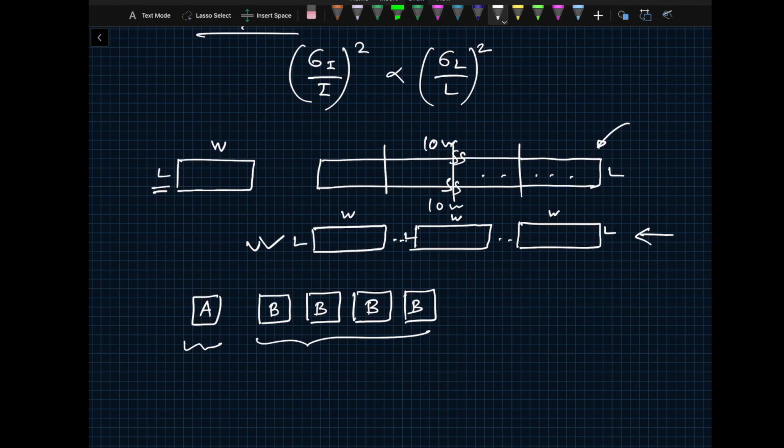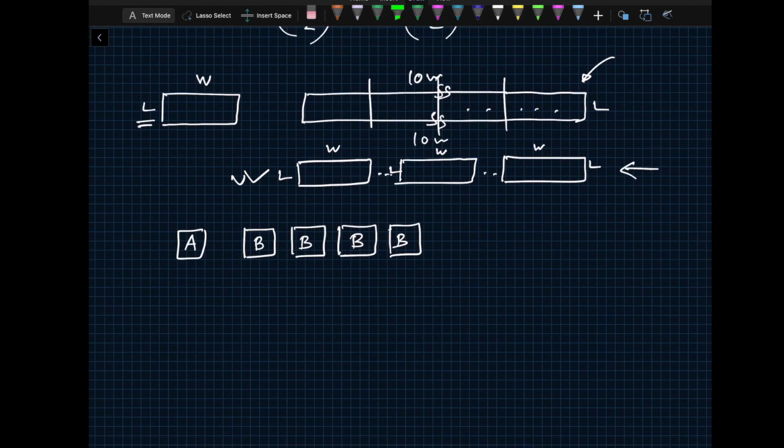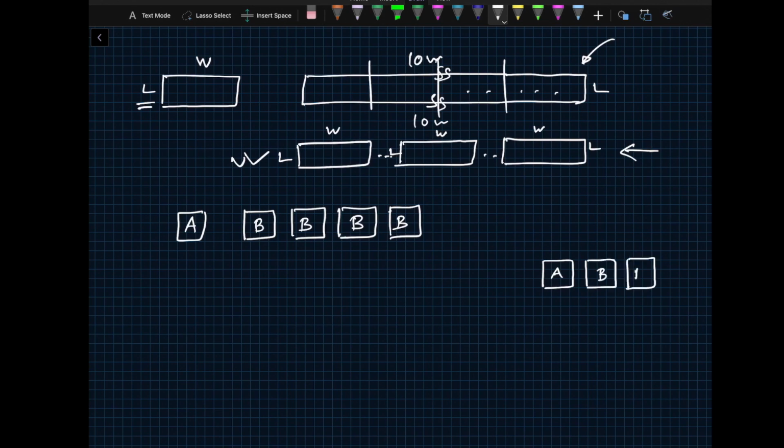So what you do is you do something called common centroid layout. In this particular class, we are not going to do any layout, but it's good to understand what's really going on. So when you lay this transistor out, it's better to lay it out this way, which is, let's say this is A. Then one way would be to draw this B on one side, and then you would draw the other B's on this side.